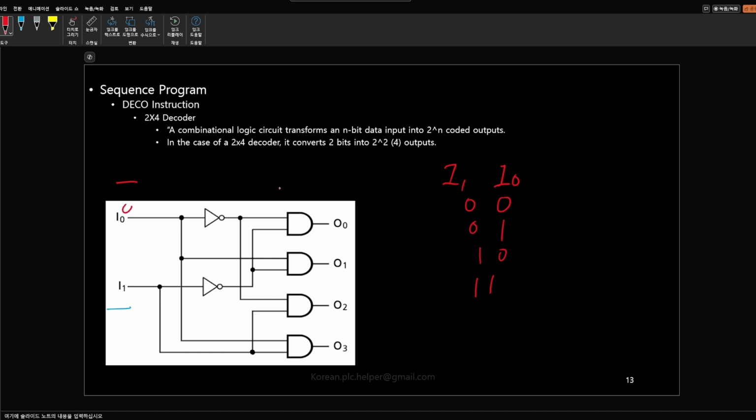The 0 from I0 travels along the line and at the first branch splits into a downward signal and one that goes straight. The downward signal splits further, and the signals that do not pass through a NOT gate remain 0.